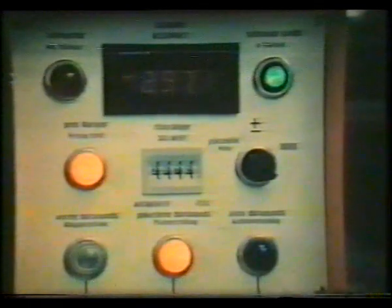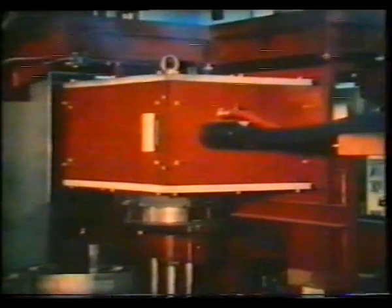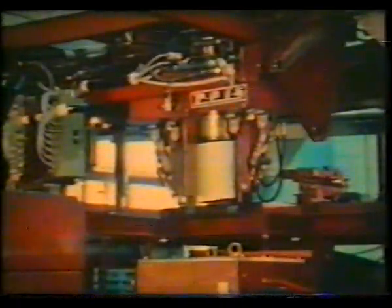As soon as the digitally displayed tolerance has been reached, the gravity conveyor carries the stack to the heating station. The laminar stacks are individually lifted into the induction coil for heating, and on attaining the required temperature, are transferred to the swivel manipulator located above. The stack is switched 90 degrees into a horizontal position.